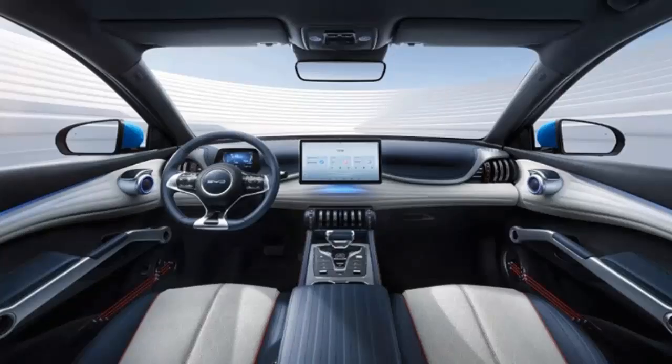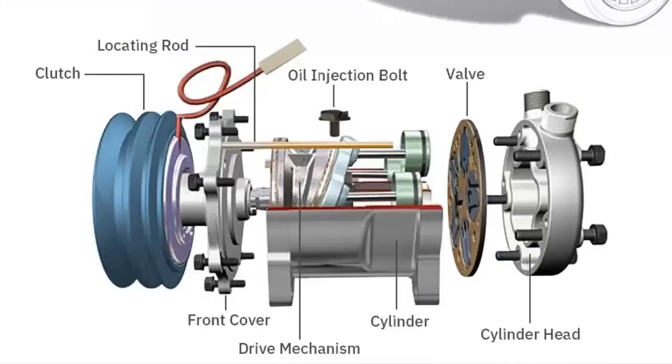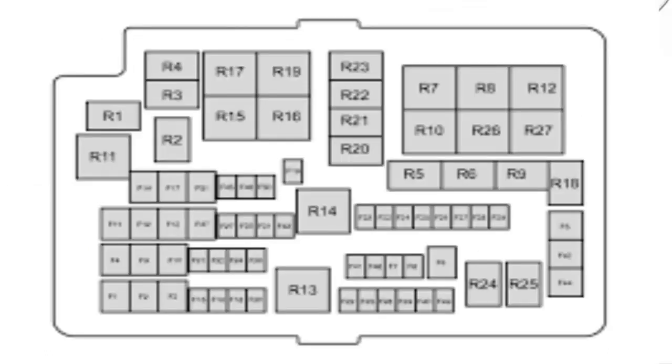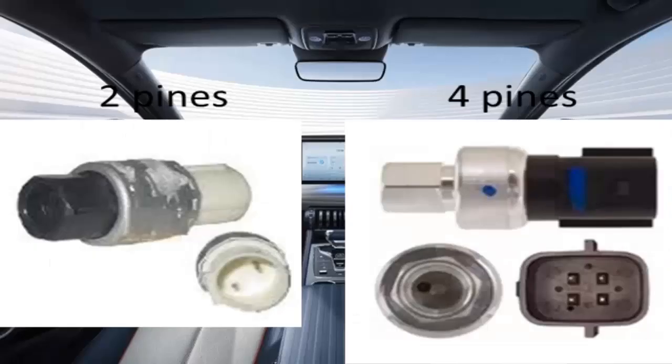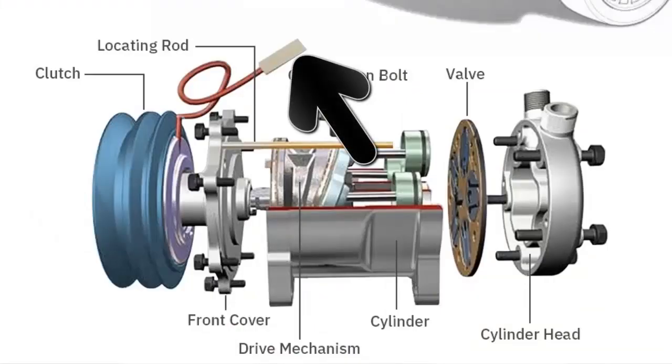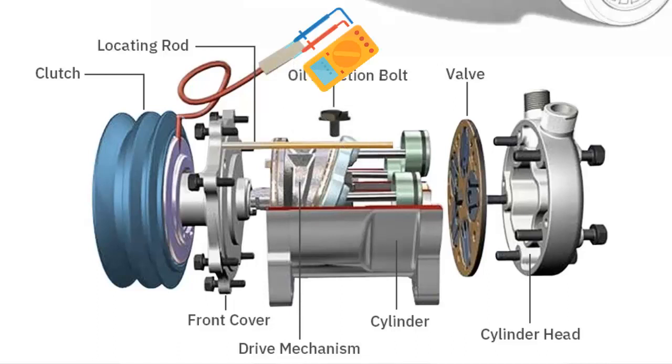If the failure is sudden, for compressors with clutches, check if, when turning on the air conditioning, you hear the pulley engagement noise that moves the compressor. If the clutch does not work, check fuses, relays, and the system pressure switch, as a faulty pressure switch can prevent power from reaching the compressor clutch. Also, check if the compressor coil receives activation voltage when turning it on, and verify the coil's electrical continuity with a digital multimeter in resistance function.